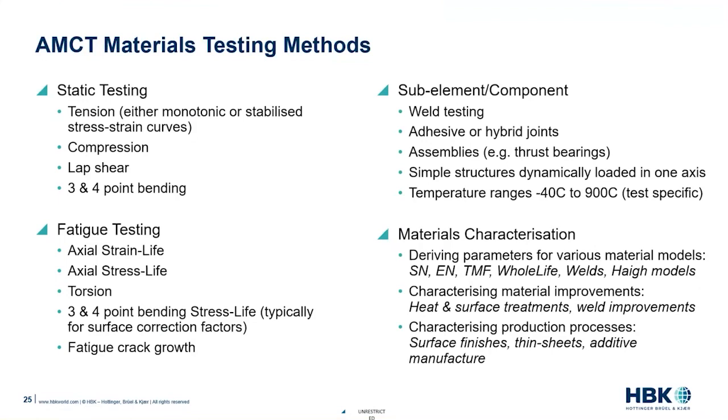So it's that characterization which is really, really important for being able to take the fatigue test results to actually characterize them into a damage model that can be used within nCode DesignLife.